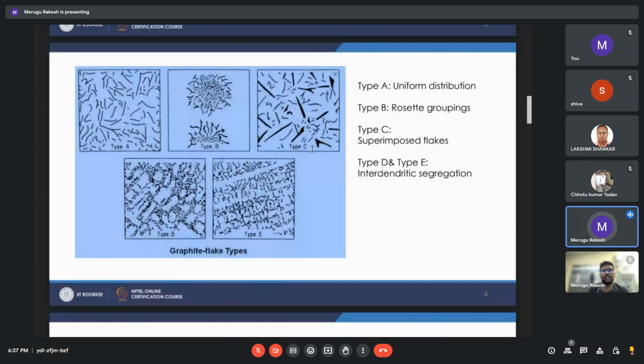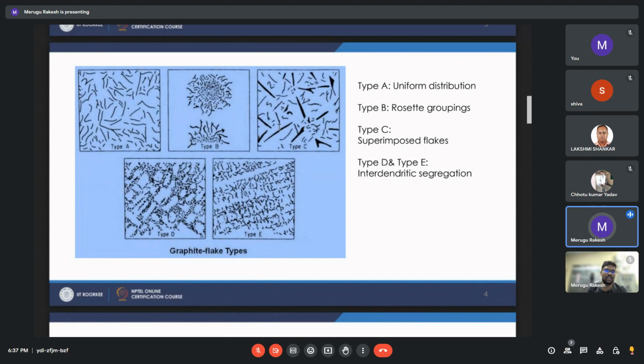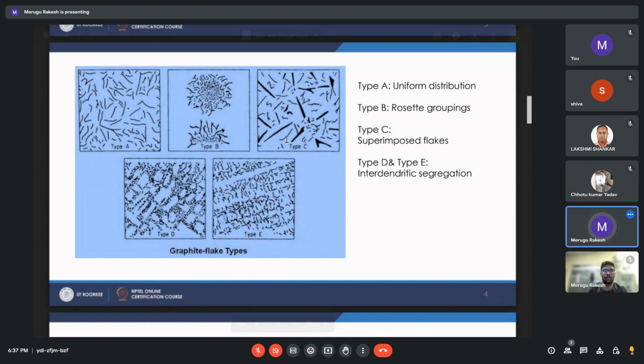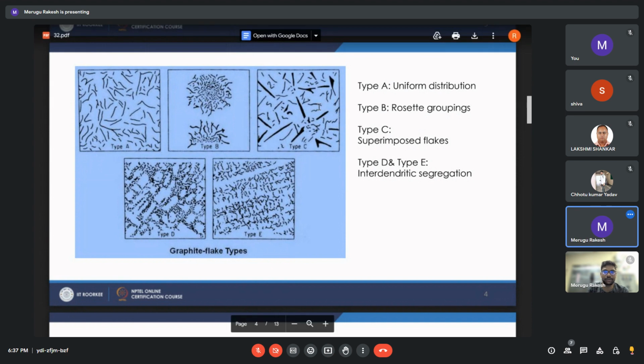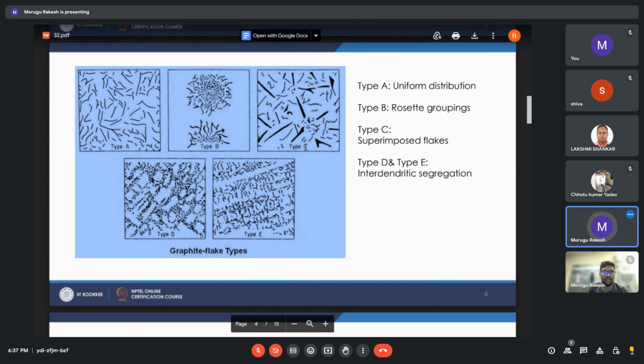Yeah, it is a very simple process. If you use some imaging process, we have very good contrast in this type of figure. Even in this simple image, and in actual microstructures also, you will have very good contrast. So if you simply apply some image processing tools, you can get the area fraction. For example, you can see the tutorials online on ImageJ for finding the area fraction. I will put it in the chat.